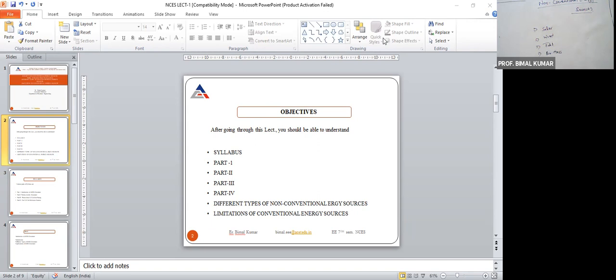So whenever due to electromagnet or due to permanent magnetism property, flux lines are there, after that we place the coil or conductor in between the north and south pole, and with the help of some mechanical means we rotate that conductor or coil, and whenever that conductor or coil rotates, it will cause the induction of d phi by dt, and due to rate of change of flux d phi by dt, EMF is induced across the coil, right?